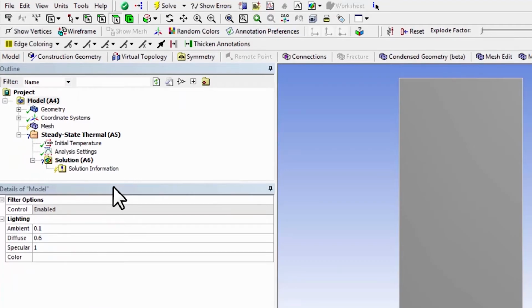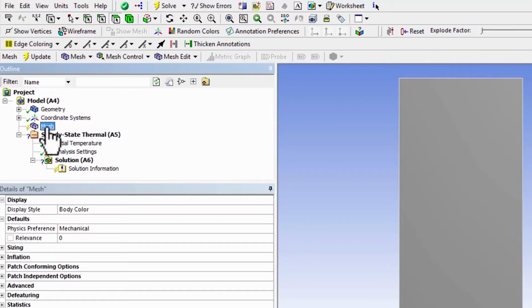After a little bit of hesitation, ANSYS Mechanical comes up, so we can specify the mesh here, and we can also specify boundary conditions and so on. So let's highlight mesh. And I usually like to throw a default mesh on it. Sometimes it doesn't work for very complex geometries, but usually it works. And then tweak that default mesh to get a more suitable mesh.